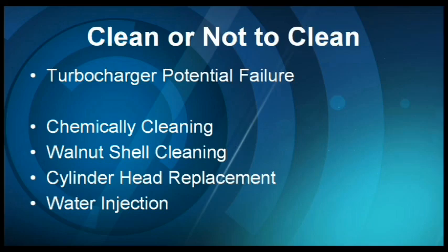You see, we don't have an injector shooting fuel to the back of the intake valve. In direct injection, it's shooting it directly into the chamber. The other option that is used by the BRZ engine, some Lexuses, known as the D4S system, has gasoline direct injection and port fuel injection.